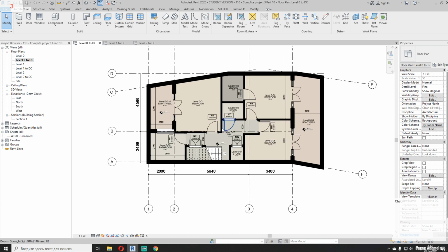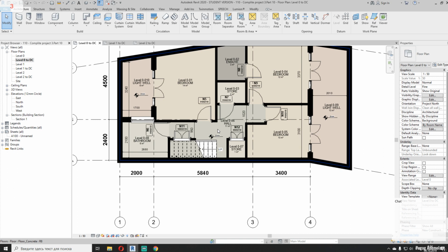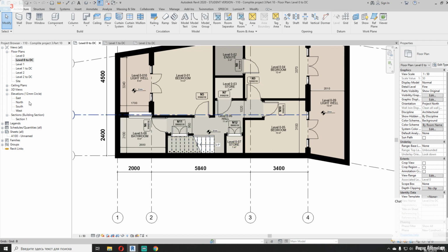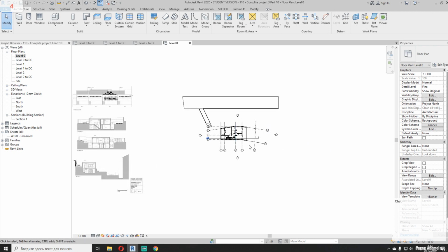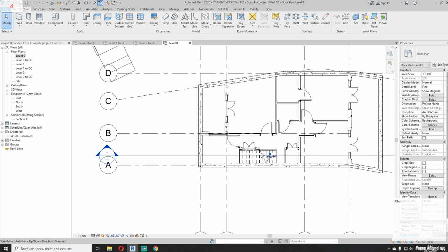Yeah, and sections. If you are an architect, your lecturer is always saying, I want the sections on the stair, so it's going on this way. So when we do the sections, actually we have one section at that stage. If I go to my working plan, as you remember, I made the drawing documentation, and this is my working plan. Let's go to the working plan and we will see my section. Here is my section, exactly cutting my stair, so this is what I want.